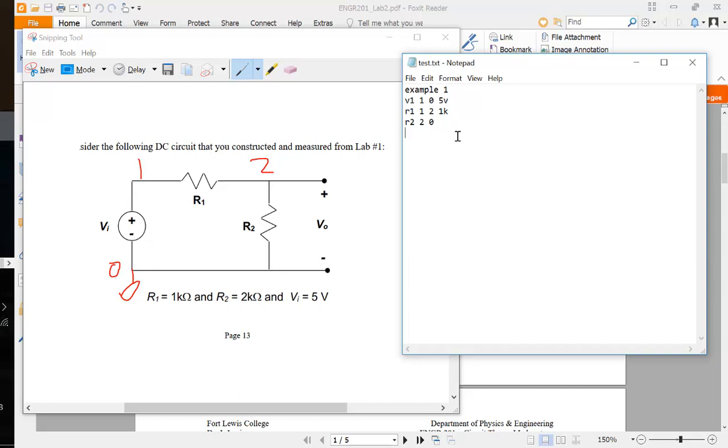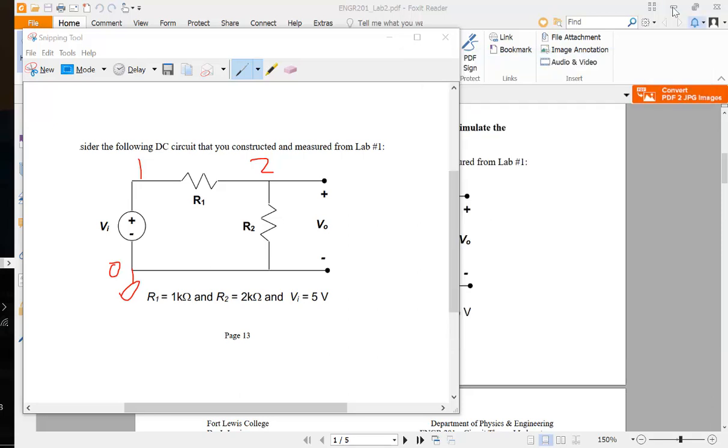And then you have to type the simulation code here. For example, we are doing a transient analysis for 1 second, right? And just save it. That's everything about the SPICE code. Okay, and I'm done with it.